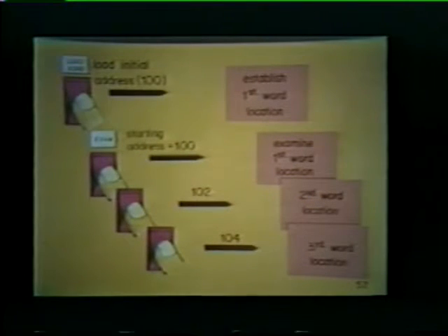The procedure for examining successive addresses is similar to the one we use to deposit data in successive addresses. The initial address is established by the load address operation, and then the examine switch is pressed. The contents of the selected location are now displayed in the data indicators. At the same time, the affected address is shown in the address indicators. If the examine switch is pressed a second time, the address is incremented and the contents of the next location are displayed. This sequence is continued as long as examine is successively pressed. We can ignore the SR configuration when pressing examine. Its contents does not affect the operation.